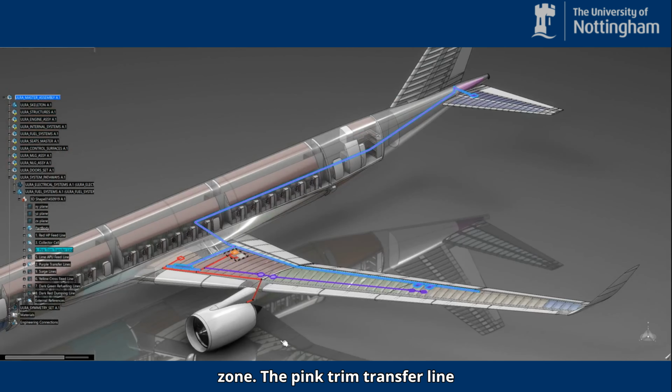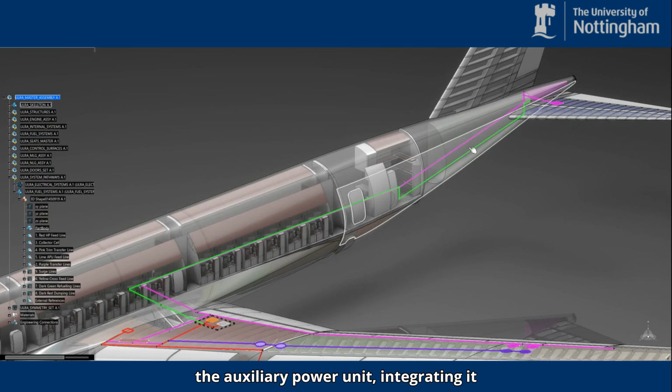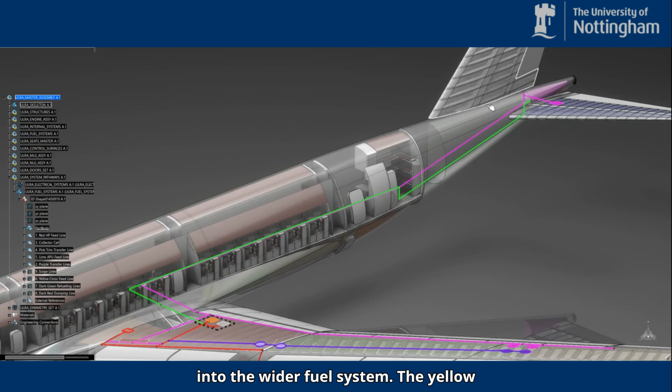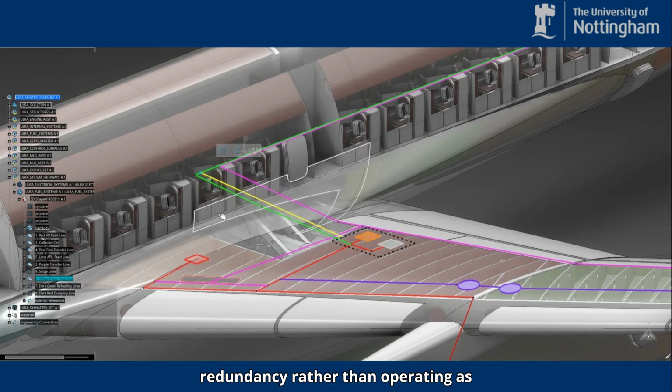The pink trim transfer line connects the main fuel system to the tail-mounted trim tank, allowing fuel to be moved longitudinally for the center of gravity control during long-range operation. The lime green APU feed line shows a dedicated branch supplying the auxiliary power unit, integrating it into the wider fuel system. The yellow cross feed line connects both sides of the aircraft, allowing fuel balancing and redundancy rather than operating as separate systems.